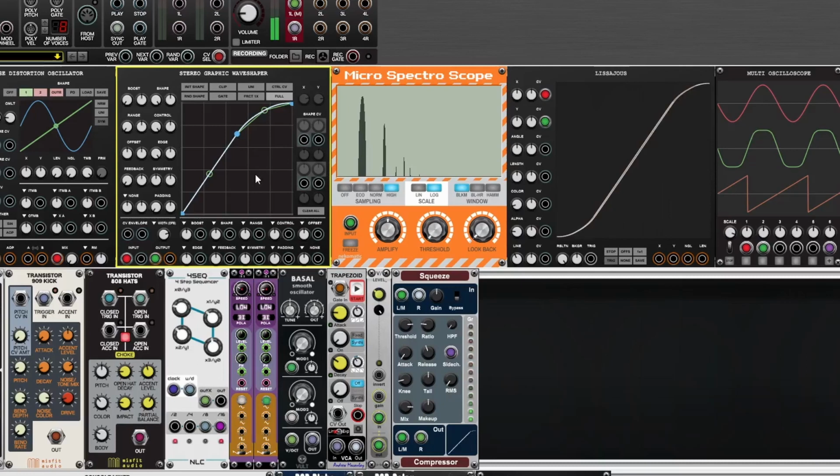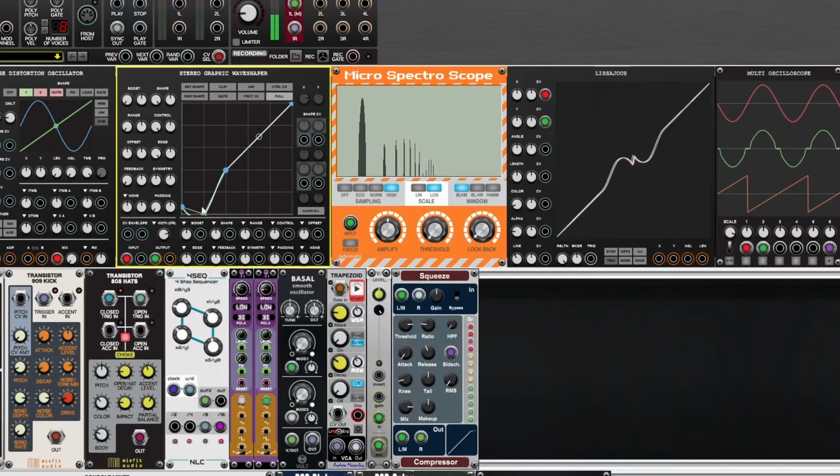With clipping, we shape the maximum value. With crossover distortion, we shape the minimum level around the 0 point. When we lower the shape around this area, close to silent sounds are attenuated further. But when we increase the mapping in this area, those sounds are amplified. This can produce some very crunchy distorted sounds.